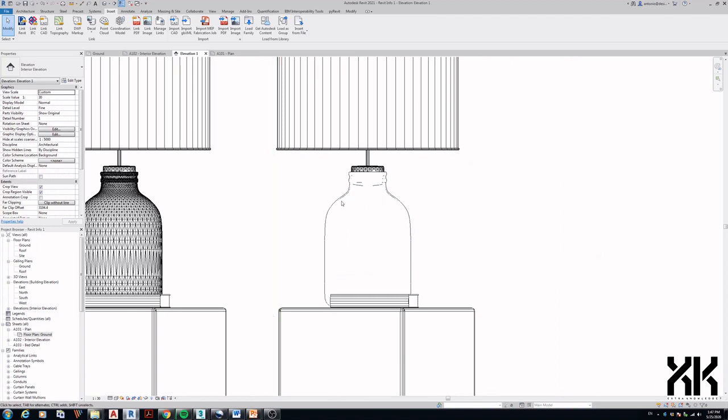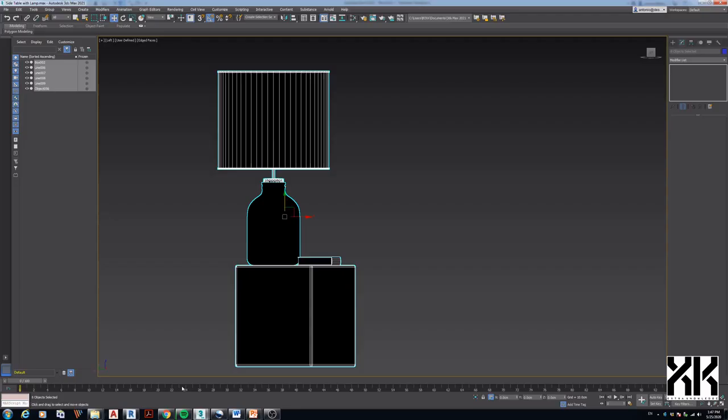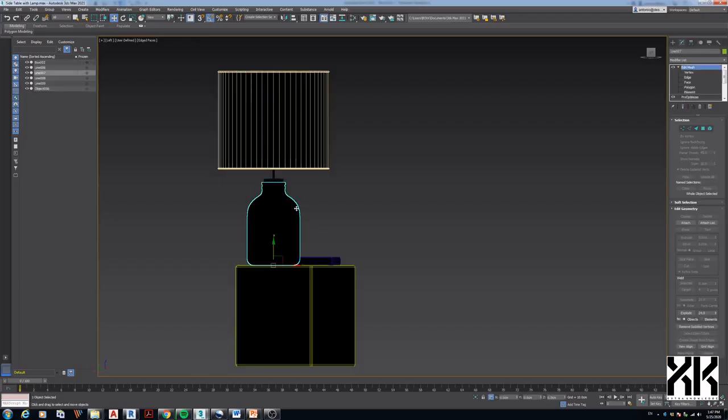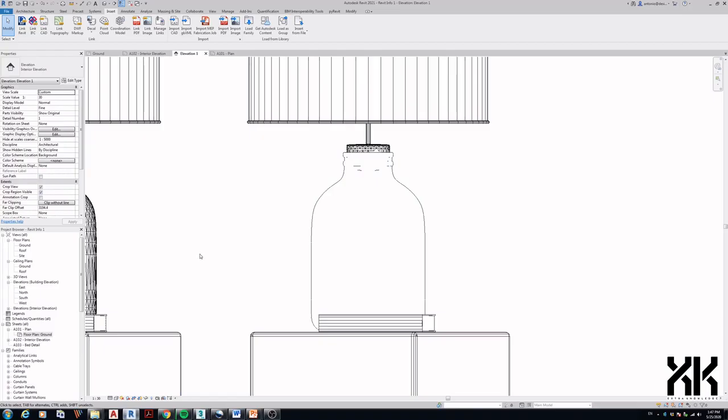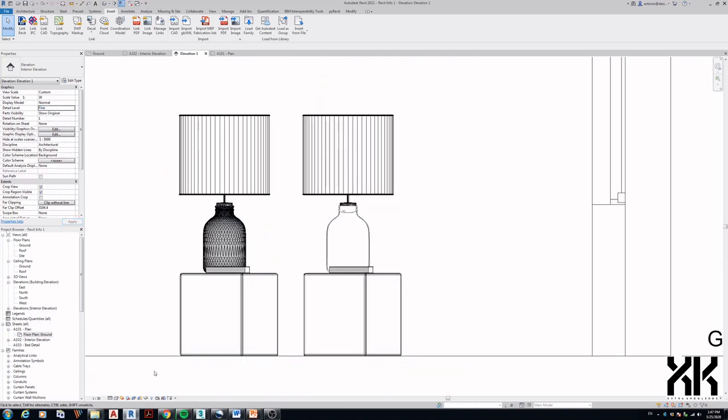The model is now acceptable for drafting, but we can still change the object definition if we want to. By doing this, we can set the detail level of the object. Let me show you the detail level list in Revit. In the View Properties panel, select the detail level. As you can see, we have three options: coarse, medium, and fine. We can see this also under the View Control bar.